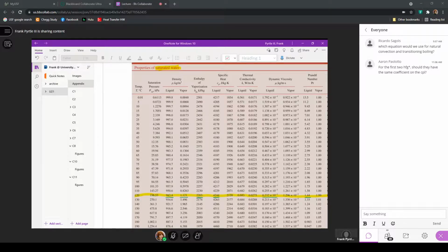So this boiling and condensation, which we've looked at on a very macroscopic level particularly in thermodynamics 2, when you're going through cycles where we have heat transfer into a working fluid, whether that be a boiler for water, or an evaporator, let's say for R134A, where we have heat transfer into the working fluid and we're changing the phase from a liquid into a vapor. We're taking advantage of the latent heat of vaporization of that working fluid.